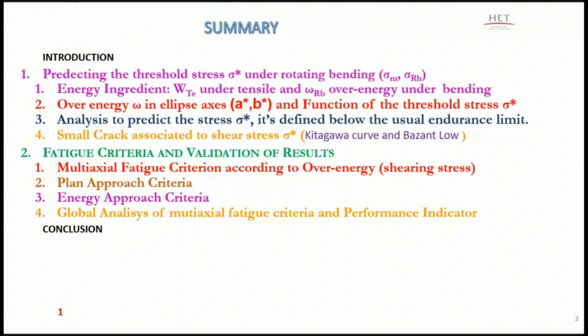I present an analysis to predict the threshold stress. This stress is defined below the usual endurance limit. In this presentation, numerical values are used to define small crack associated to shear stress with the Kitagawa curve and Bazant law.